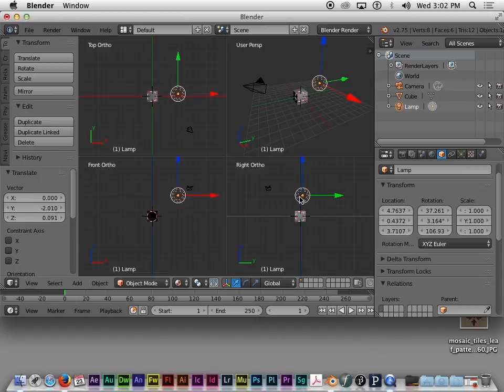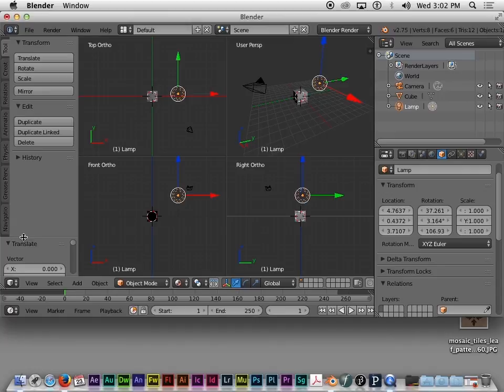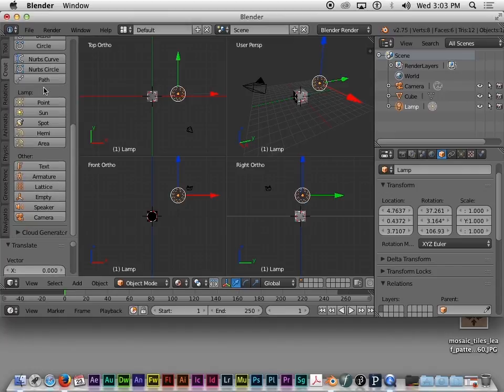All right, so let's do this. Let's add a couple extra lights to the scene now. So does anybody remember how we add extra things into the scene? Possibly the add button. Good job. Add. What else? One more. Lamp. Create. Yay. And create is the one that's in your tool shelf on the left side of the screen. It's a tab that says create. So look over on the left for that left-hand toolbar and find the one that says create.